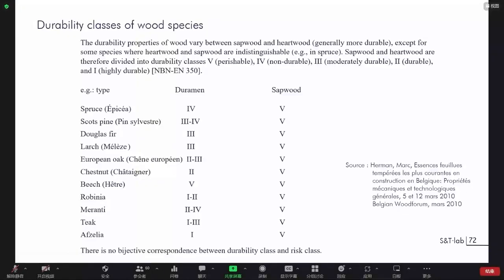And indeed, you also have this characteristic that timber with the sapwood won't be resistant at all. So you have to decide if you want to remove it or not. And depending on what the heartwood in the middle is, you will have resisting or not resisting timber.